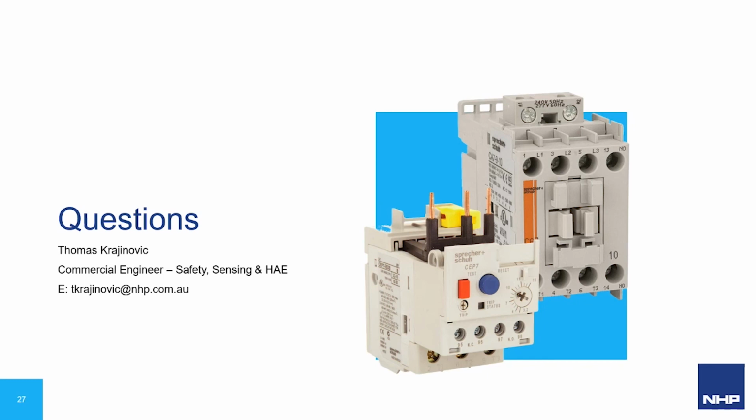So it is possible. I was just going to say as well, it's also possible to use a product that's not necessarily hazardous area rated within the hazardous area, but that's provided it's classified as a simple apparatus, which just means it can effectively only have dry contacts, no circuit boards or anything like that. Yep. And you would then need to use this with a barrier to make sure that the dry contacts are suitable for use within the hazardous area. But you definitely can have products that combine both hazardous area protection methods and are safety rated as well.